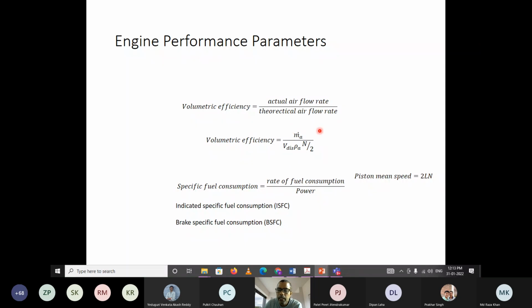There, the mass flow rate of the air is measured through the throttling method, depending upon information from the sensors, like how much the throttle is opened, what is the intake manifold pressure, what is the intake manifold air temperature, engine speed, and the engine geometry. If your ECU, engine control unit, is getting all this information, then the ECU could calculate online what the mass flow rate of the air is, but that normally does not happen.